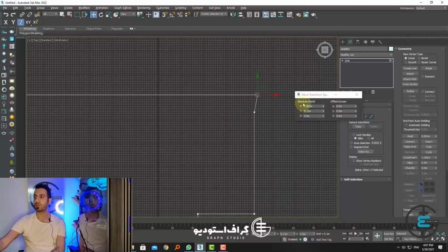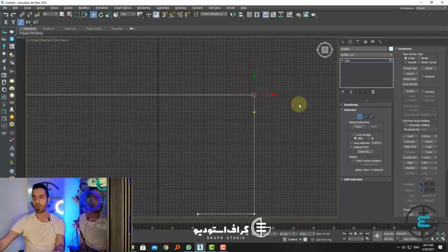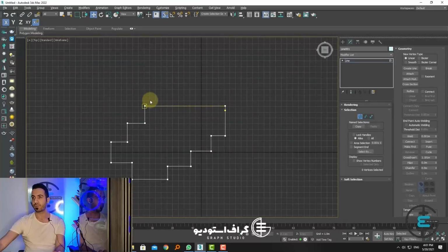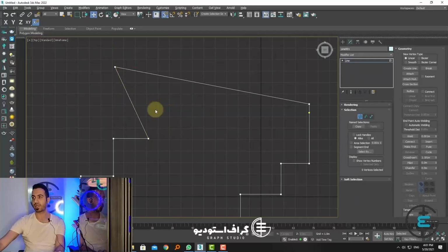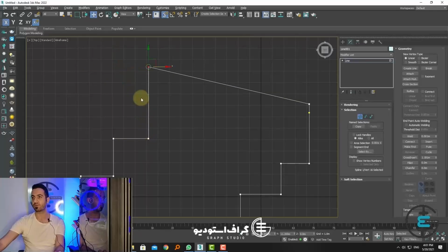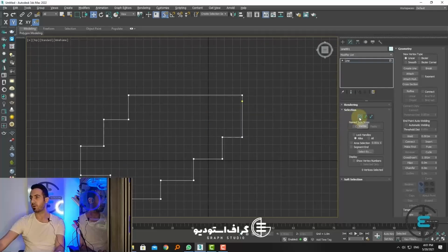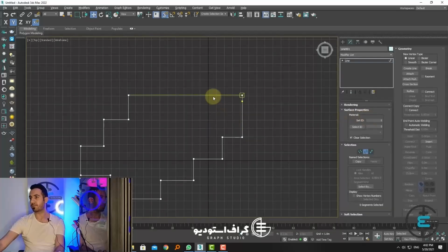Well, we wanted to take help from refine, so I'll now go to the segment section. I activate the refine option. Guys, refine also works very well with snap. Here, for example, you can say that it should also be active on the midpoint. I should now exactly put a vertex in the middle. Guys, here in refine, we add a point to any place we want, and when we apply the extrude operation to this, the same point seems to have a connection after giving volume to us. So here I can close the snap now.